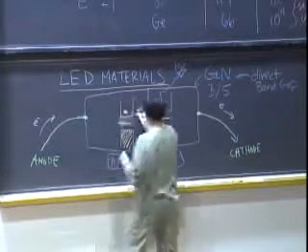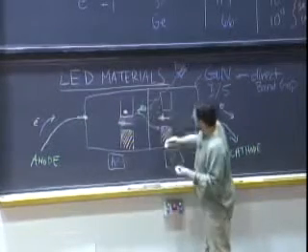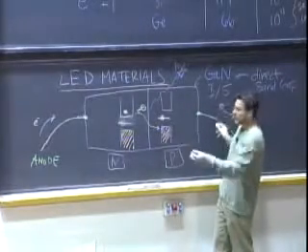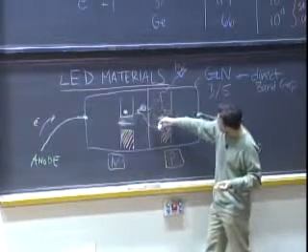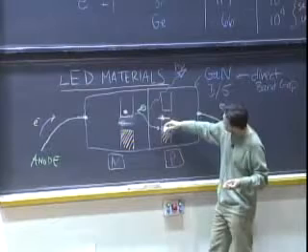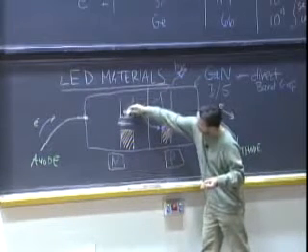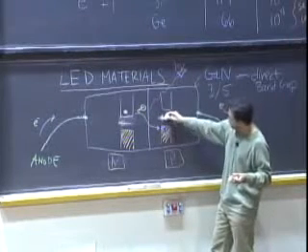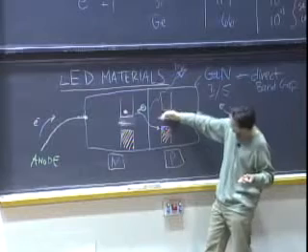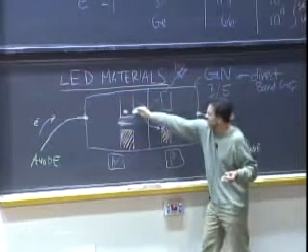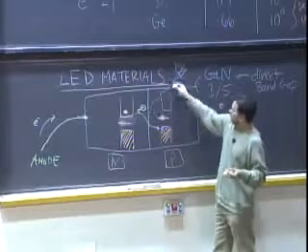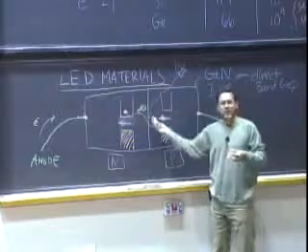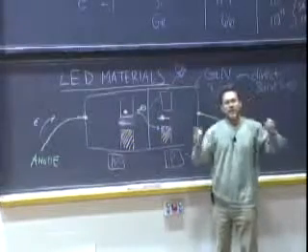Electrons flow down there across the interface, and when you hook this LED up to your potential difference supply, the electron flow is unidirectional. As the electrons jump across the interface, they're going from the conduction band of the N-type semiconductor. They're going down in here. Holes are being created. Maybe electrons are being pulled right off of that boron, and they're moving right across here in a process that leads to the emission of light right at the interface. So it's like a waterfall of electrons taking place all along this 2D interface.